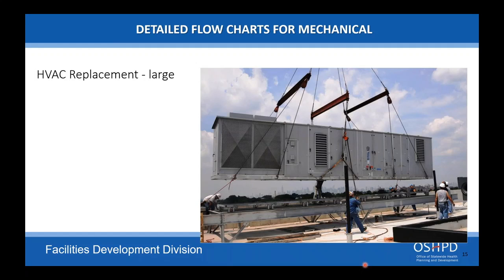And there are requirements that this would be comparable to the unit being removed. And if you have specific questions on that, you can contact us, but we're going to be looking at the CFM capacity, the tons, all that, the weight of the unit itself to make sure that it will work with the same support structure.